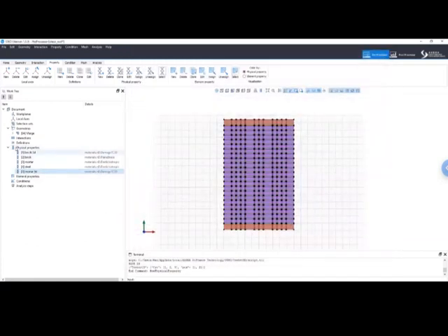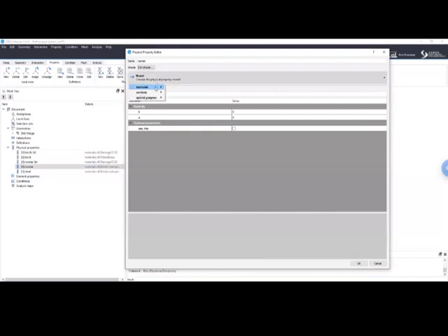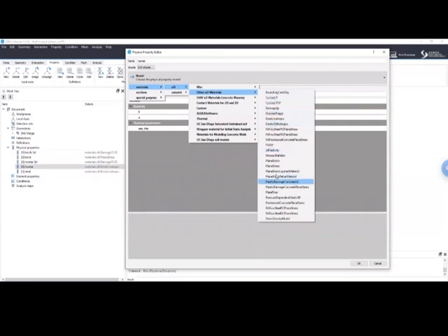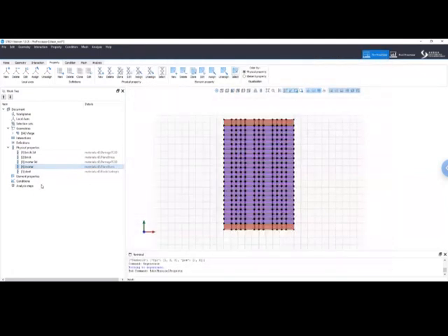So we move it up because it should be defined before this one. Otherwise, this one cannot be converted into a plane stress. So let me move it up to the mortar. And then, as we did before, we convert the mortar that we defined before into a plane stress adapter. So we go under ND material, we choose plane stress, and we choose as the 3-dimensional model the mortar 3D. Perfect. So now we are fine with the material models. We have a two-dimensional brick here, two-dimensional mortar here, and then we have the steel model. We are fine, let's save it.